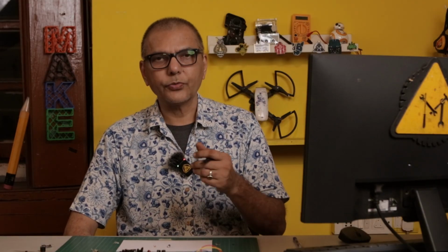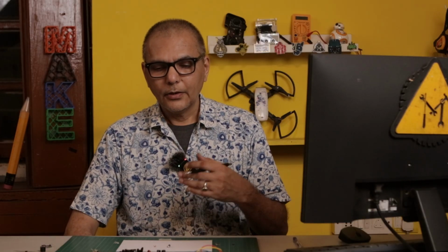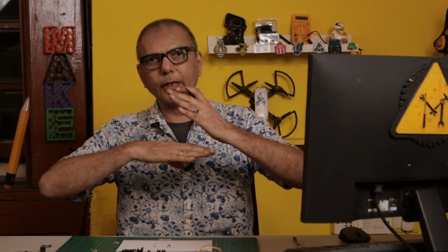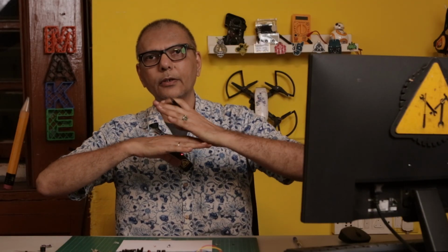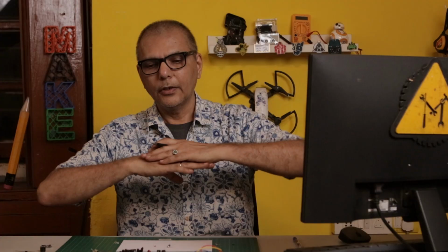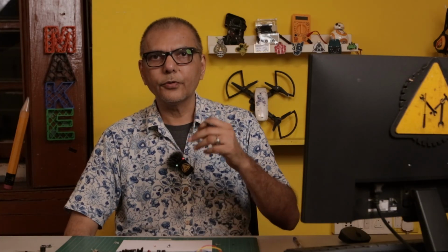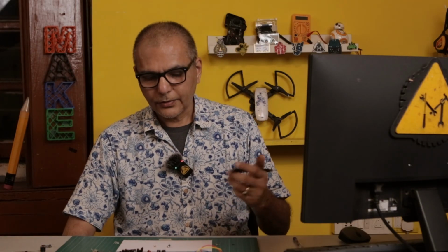If you have, let's say, a switch or a push button that's connected to an Arduino, you will notice that when you press the switch, you will get multiple switch events being recorded by the Arduino. That's an effect known as debounce. So when the switch closes, because it's a mechanical device, it will close and open and close again a couple of times before it settles. So that's debounce. The switch is moving pretty fast, and each of those events gets recorded as multiple switch presses by the Arduino. So you want to avoid that.